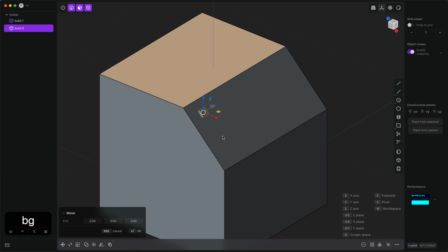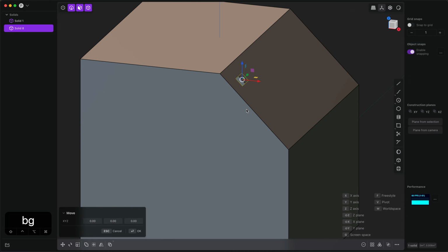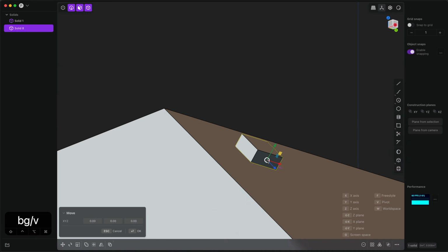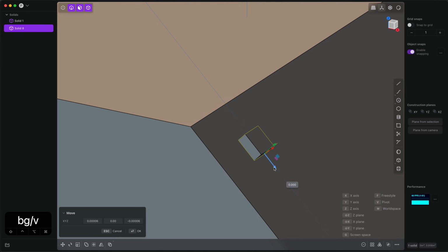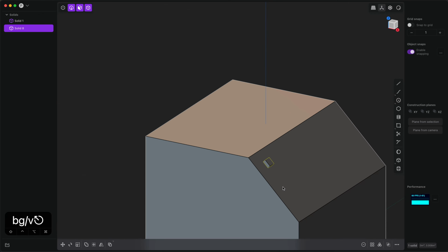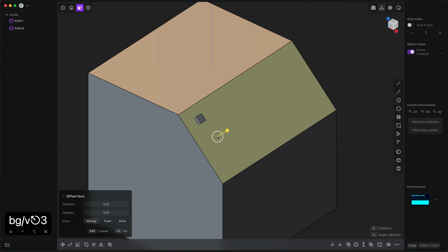But let's say we wanna move it, well, not along Y, not along Z. Let's say we wanna move it down this face, right? So none of these are aligned in the way that we want. Now we can definitely use pivot and set a local Z to move it along the face, right? But another option, if we're gonna be doing this over and over and over, is to actually make the face our construction plane. And we can do that by selecting a face and typing space.